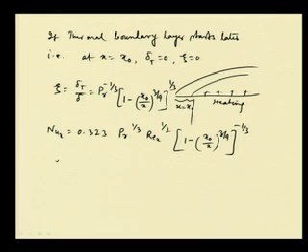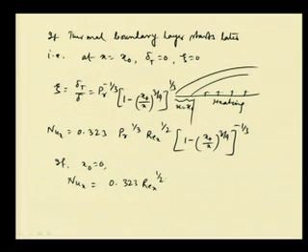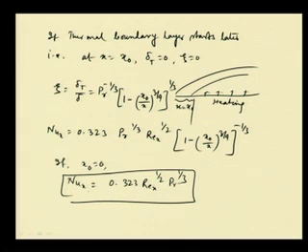Then if x naught equals 0, Nusselt x is equal to 0.323 Reynolds x to the power half and Prandtl to the power 1/3. So, if it happens like this, the Nusselt number is going to be of this expression, and if x naught equals 0, that means it coincides with the starting point of the hydrodynamic boundary layer, under that situation the Nusselt number again comes back to the original equation. That is what we have discussed.